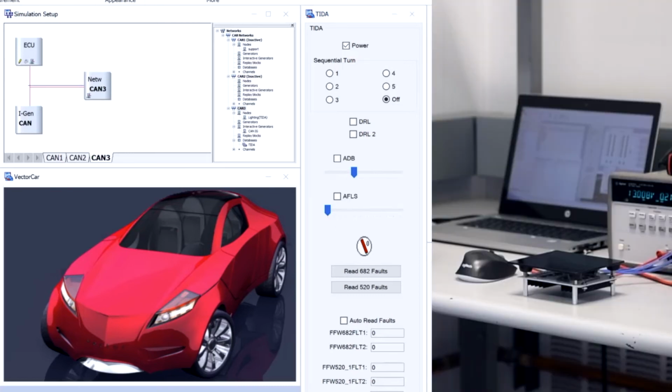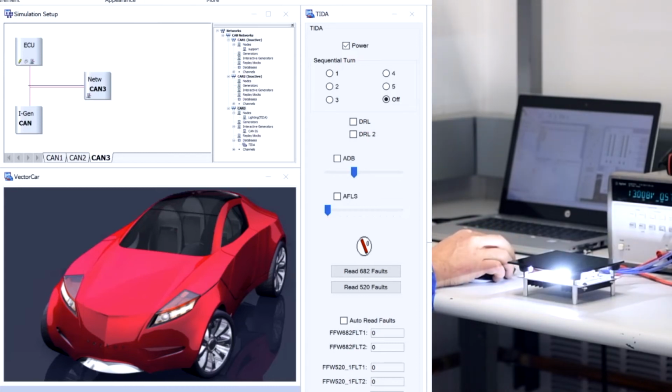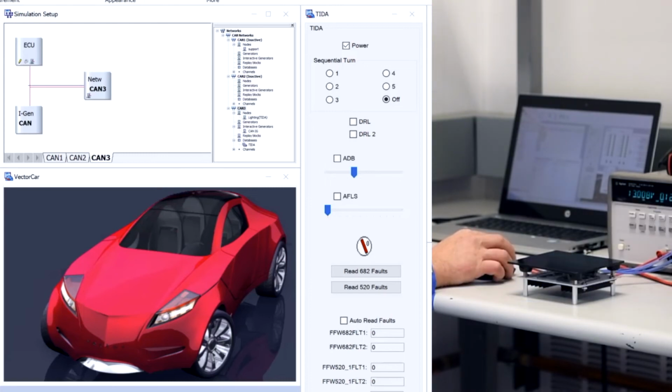Finally, we have real-time pixel level control of each headlamp LED, which is needed for adaptive headlight functions, which automatically adjust the intensity of light emitted from the headlamp based off real-time inputs from the vehicle's front-facing camera. Examples of adaptive headlight functions include cornering lights illuminating the road based on the steering angle, detecting and illuminating road obstructions, and creating anti-glare zones to prevent blinding oncoming traffic.